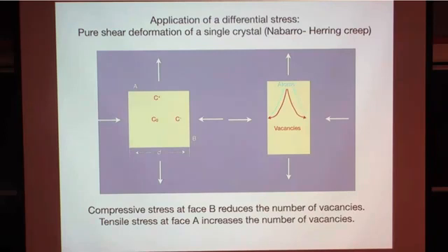So the very basics, thermodynamically you can show that you have point defects. The important point here is that a stress interacts with the point defect density, right? So that's the point to keep in mind. The rest is then more or less geometry, how you diffuse and properly account for everything. But the important point is that stress causes a change in concentration and therefore causes diffusion, right?